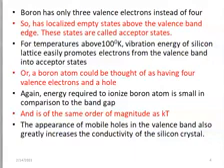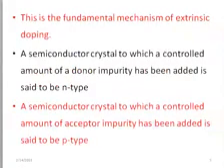So the hole is like a positive charge, because the electron is what? Negative. When a hole and an electron are combined, they cancel one another, because the hole is positive while the electron is negative. So in the case of introducing a group 5 element, we create what we call an N-type, that is, negative type semiconductor, because we have excess electrons, which are negative in charge. But where we introduce a group 3 element like boron, we have a hole, and that hole is positive, so we call that semiconductor a p-type semiconductor, which means positive.